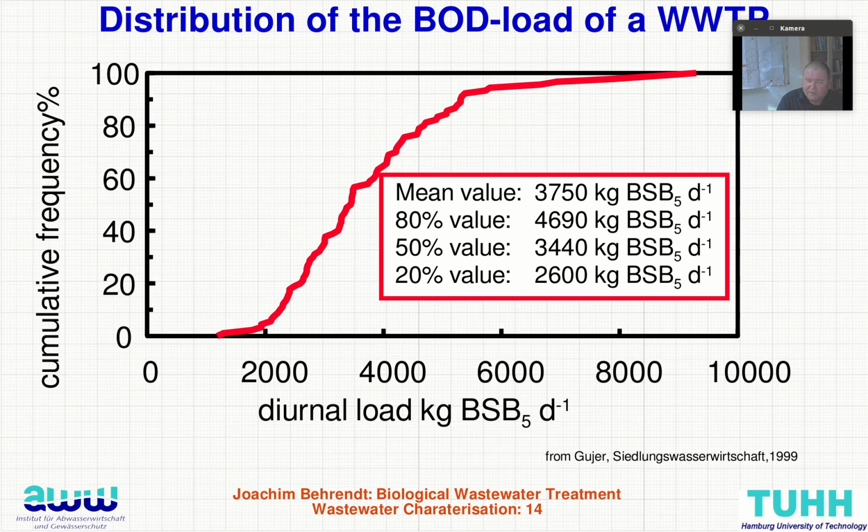Yes, and this is quite an important approach for statistical dimensioning, to determine the parameter for the calculation of the dimension of a tank volume, for example. If we go to the stormwater event at the highest level, then we have in this case 9,000 kilograms, and this would be double the amount, finally resulting in very huge volumes for the treatment plant.